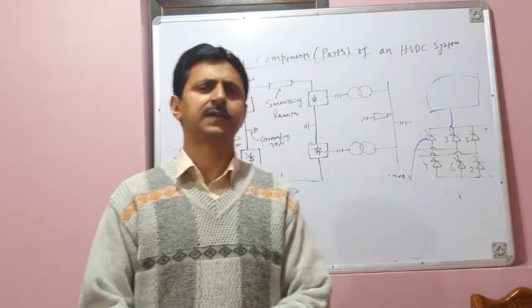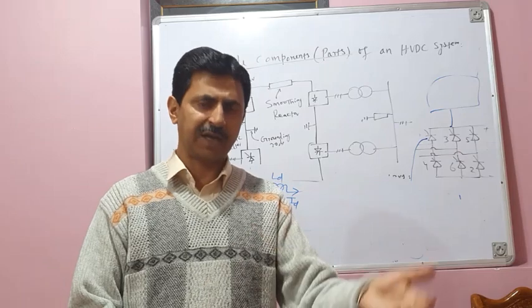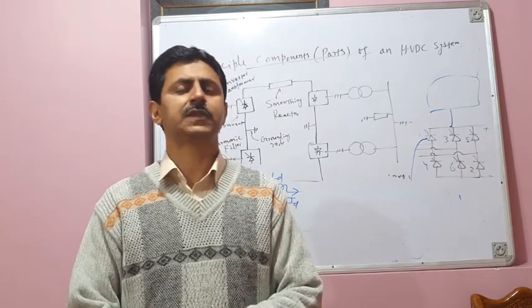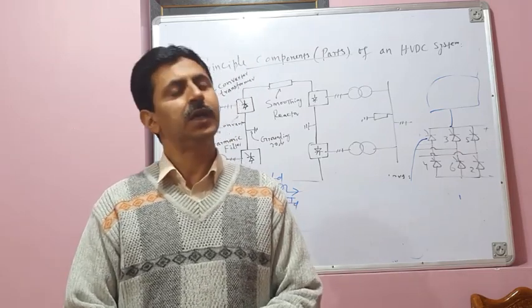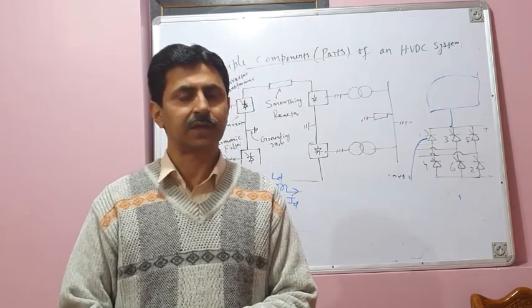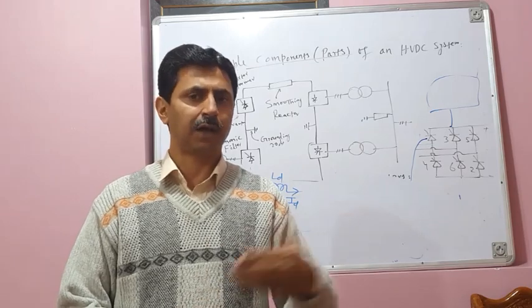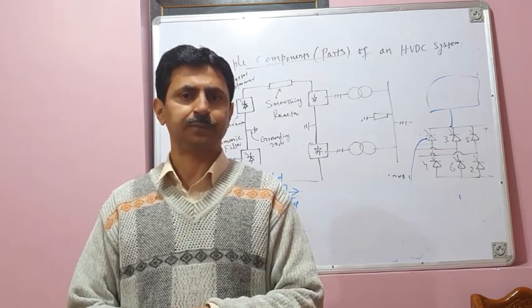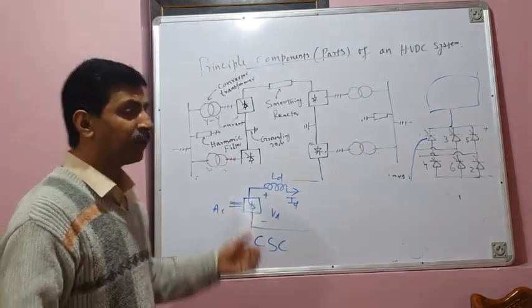And the converters, semiconductor full converters, which you have studied in your basic power electronics course, they are all current source converters. Because if you remember, in those converters, we are not using a capacitor at the output, we are using an inductor at the output, right? And what about the voltage source converter?